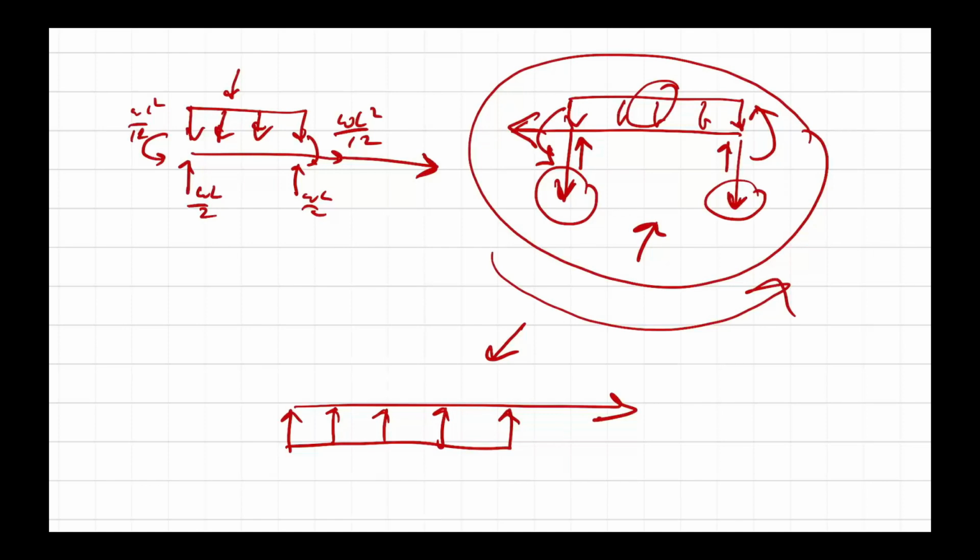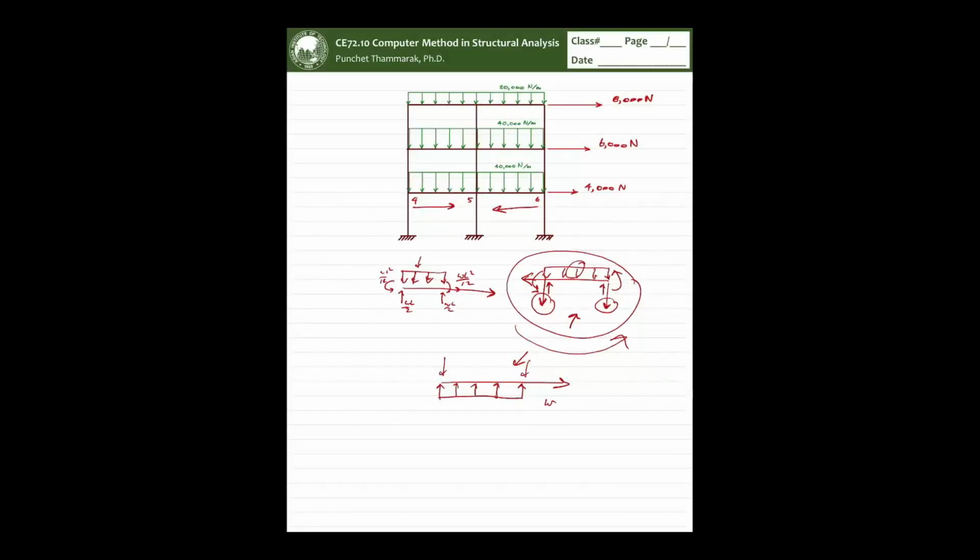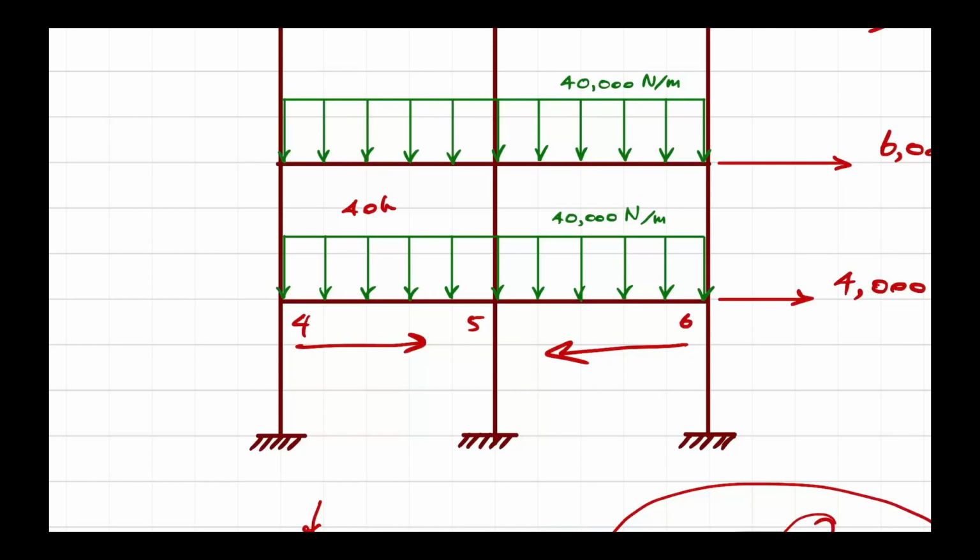If I turn my head upside down to see this picture, generally we have the load coming downward. Now, in this case, as we set up the local coordinate like this, you're going to see the load coming upward. As the load is coming upward, your fixed end reaction will be on the opposite side. So the W we apply in this case here is 40k Newton. In this case, minus 40k Newton. This is associated with the way we set up the starting and ending node.